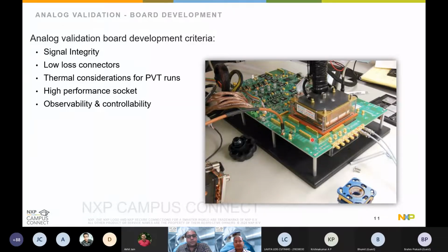So let's say I see some deviation in an electrical measurement, and I have to start debugging that. The best way to do it is blockwise or stepwise, so at every step we need to have some connector so that we know the quality of the signal at the end of each phase or each block. So observability is really critical there, and controllability.